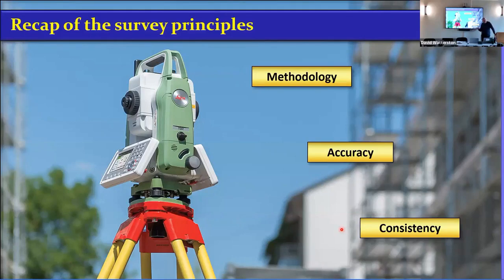And then, because to put the concrete base down you've got to have shuttering, the chippies and the ground workers were setting up the shuttering. So I was coming along, set up my instrument, rolled it, banged it with my laser. Remember, the laser's 1 millimeter accuracy at 1 meter. I says, you're 2 mils out. Can you change that one? And that one there's 5 mils out. He went, what? I says, well, yeah. He says, what do you think we're building? A Swiss watch. I says, well, you might say that, mate, but it's almost like a Swiss watch.